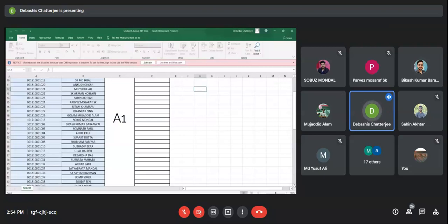Sir, could you repeat the design criterion once again? Maximum efficiency. Sir, will you repeat the parameters once again slowly? Okay, 3 phase, 415 volt, 50 hertz, 1500 watt, 735 RPM, 0.85 power factor, 45 degree centigrade temperature rise, and for maximum efficiency. Okay, sir, got it.